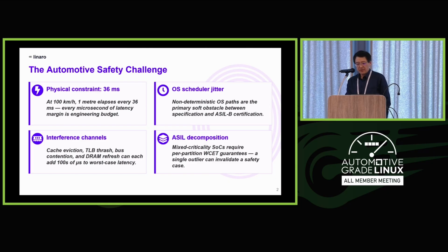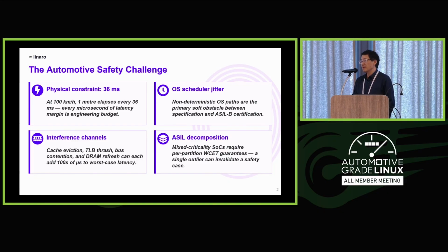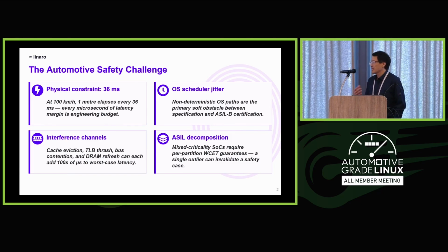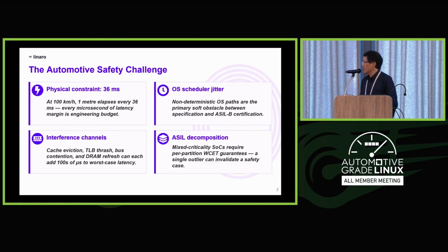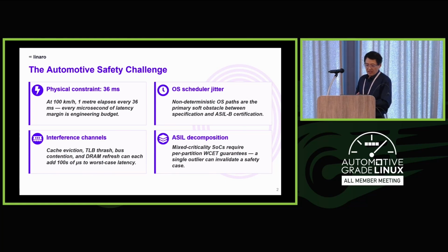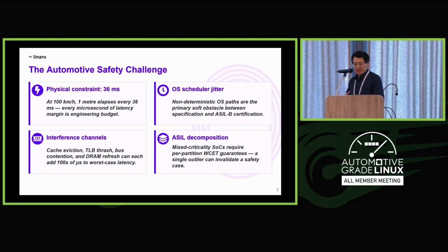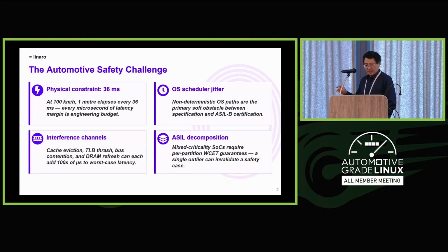But think about this. On the underlying hardware side, modern SoCs have become so complex, with a lot of non-deterministic behavior, such as the pipeline, the cache effect, and dynamic interconnect across different IP blocks. This brings a lot of uncertainty and interferes with the safety application. So this is one aspect, coming from the underlying high performance SoC.